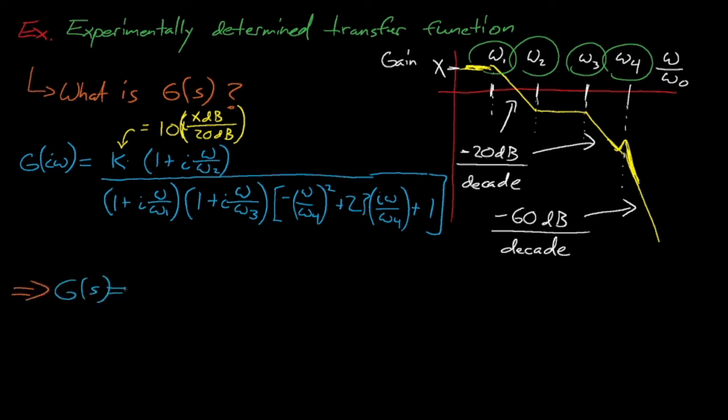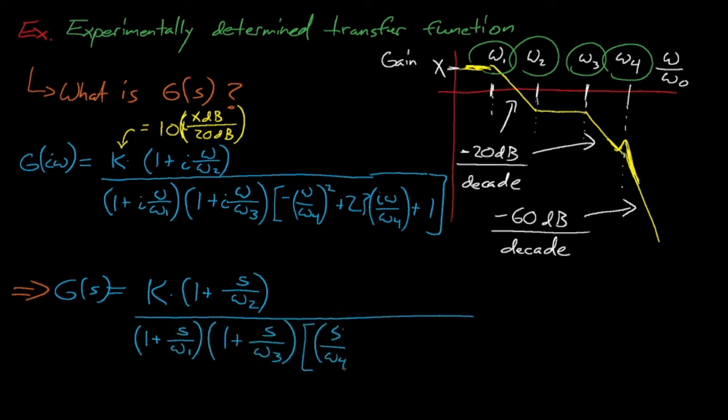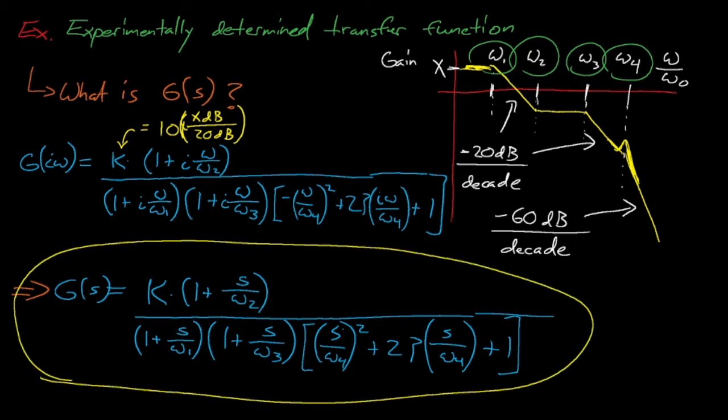So by looking at this one Bode plot and tracing the different values of omega naught, we have revealed the transfer function for a system that is some product of 4 different polynomials, I guess technically 5 if we include the gain. We get all of this just by looking at one Bode plot.